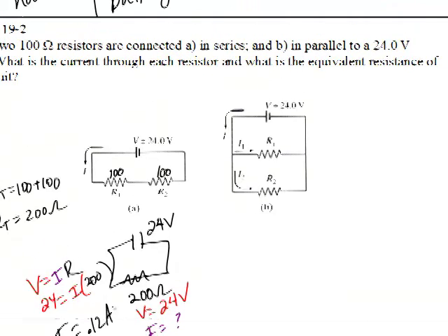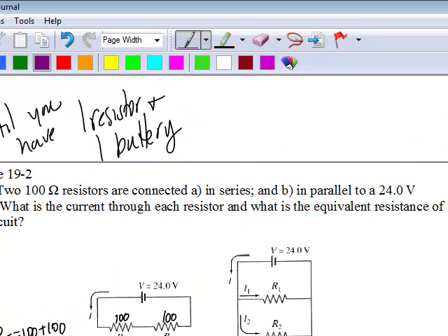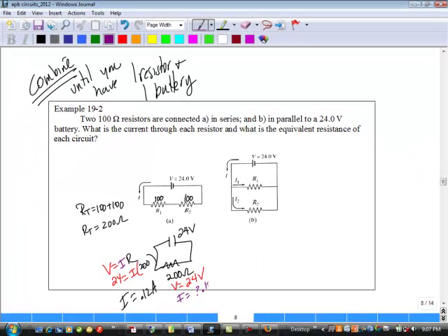So, as I go back up, I know the current because one of these two numbers is going to stay the same. What is going to stay the same, V or I in series? If you don't know, look it up. I stays the same. So I write down my I because I know it has to stay 0.12 amps. Then when I do the math, I can see the voltage here will be 12 volts. The volts here will be 12 volts.